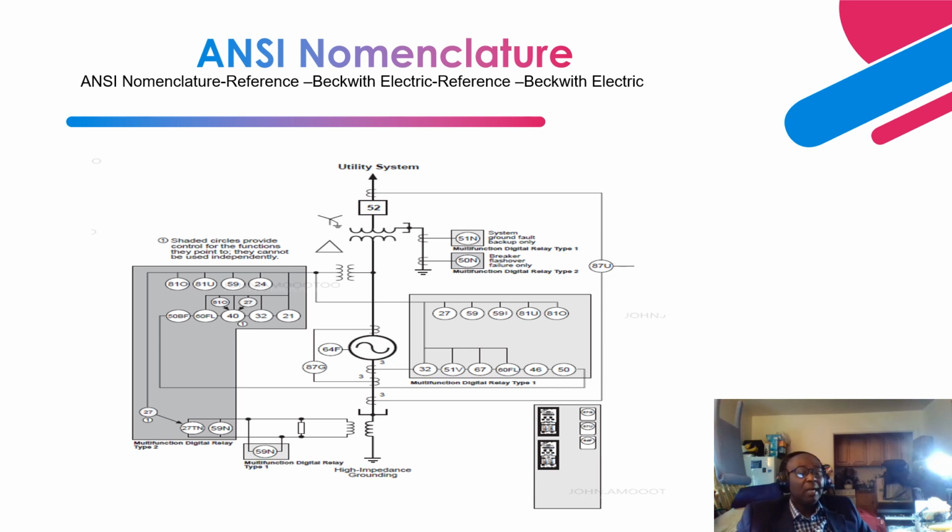Let's say 60.5 hertz or 61 hertz. Beyond that, operating beyond that is going to be timed, and after that, you're supposed to trip the generator. Similarly, for 81U, which is the frequency element, let's say you have a 60 hertz nominal operating frequency of a generator, and the manufacturer is going to allow you a tolerable range of 58.5 hertz to 60 hertz. Beyond 58.5 hertz, definitely the manufacturer will put a timing in it and basically trip the generator offline.